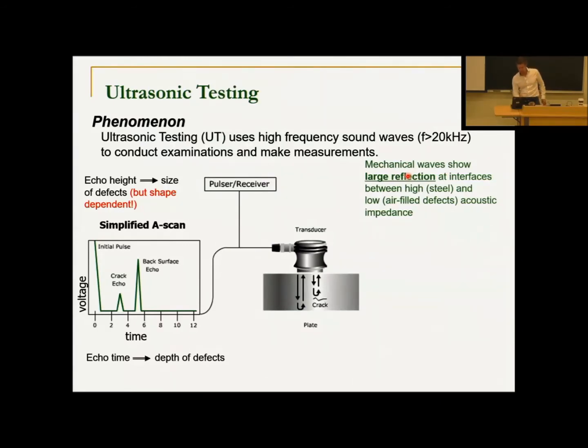And when we have a reflection, we see in this diagram here, we send a wave in a certain direction and we look for the return echo. And if the return echo is somehow changed, it comes sooner, we know that there must be something here that's reflecting that energy, and it's probably some sort of air-filled defect like a crack or a void.